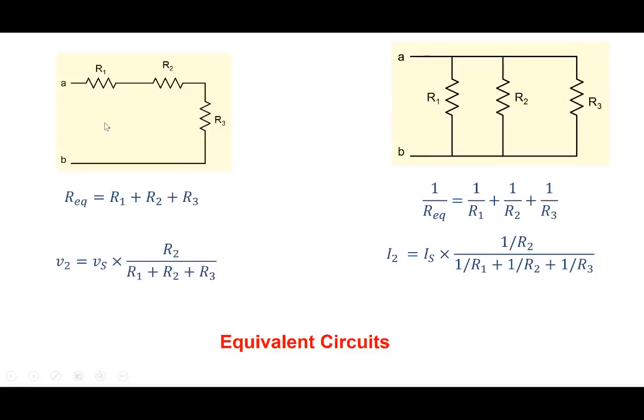So what we have learned are things that you're already familiar with, the concept of equivalent circuits. That series connected circuits can be described by a single resistor. Parallel connected elements can be derived by one single resistor. Concept of voltage division, concept of current division. Simple results, but you can apply them in many places and you can use them to your advantage here.